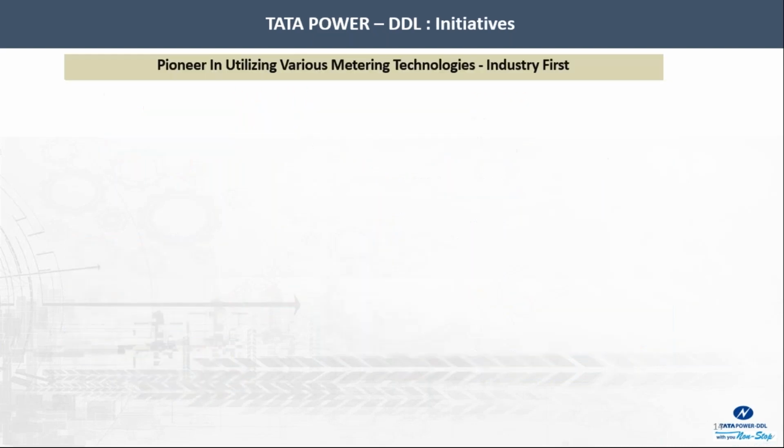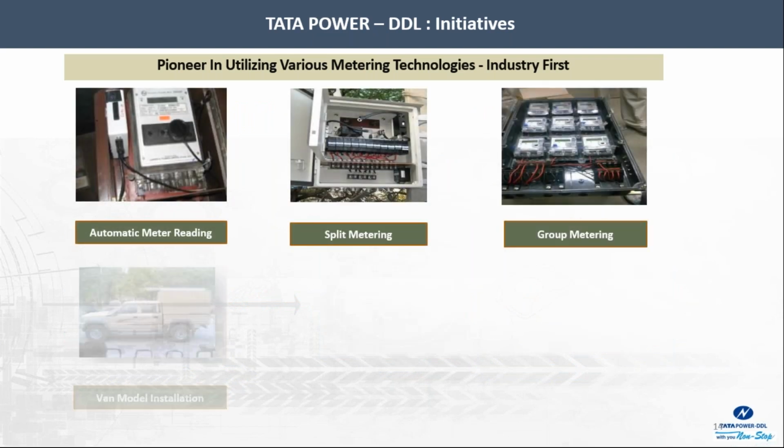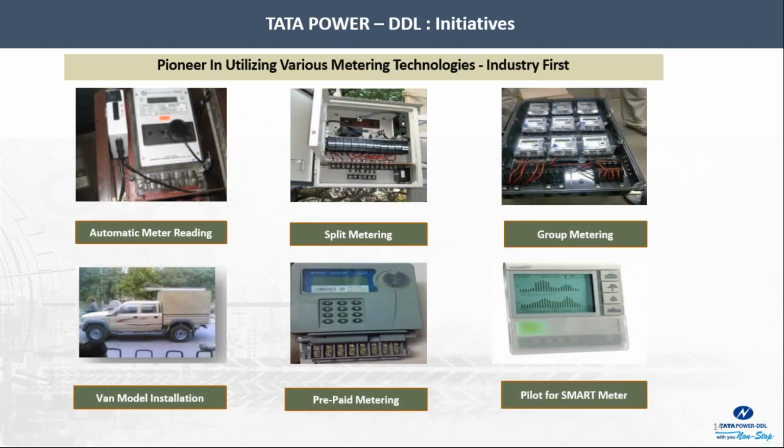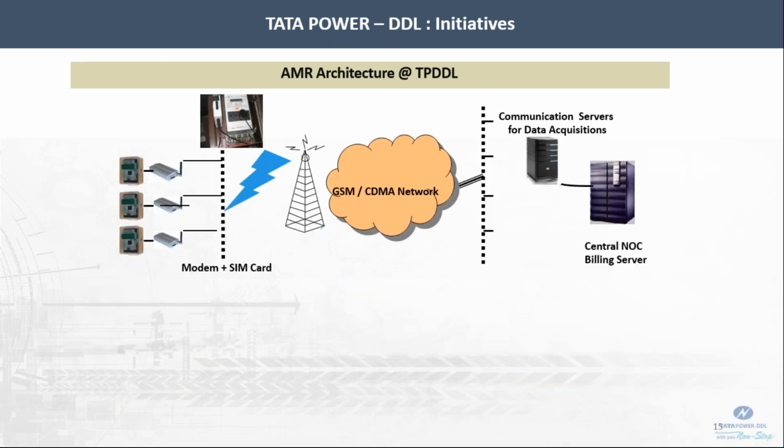If you go to the next slide, then I have just mentioned how we are using automated metering reading system. And for the normal consumer, we use a mobile metering system where he goes, he punches the meter reading, and it then does some validation checks with the SAP billing system in data center, and has those kind of quality checks so that someone cannot punch the wrong reading.